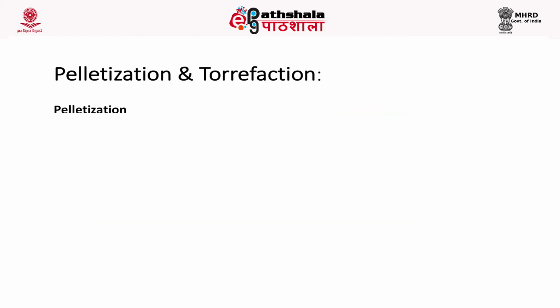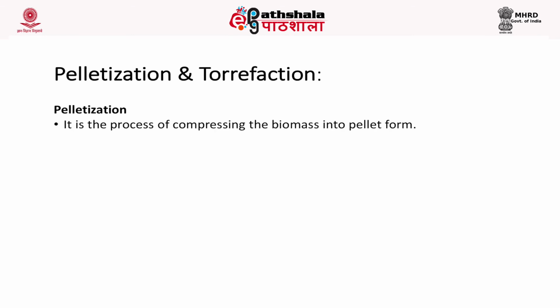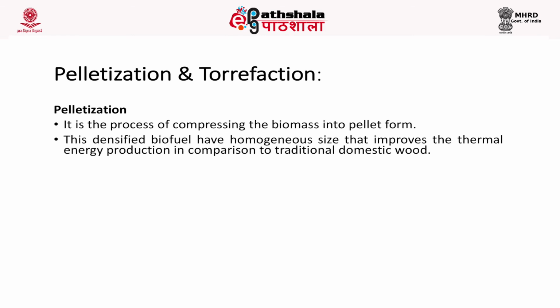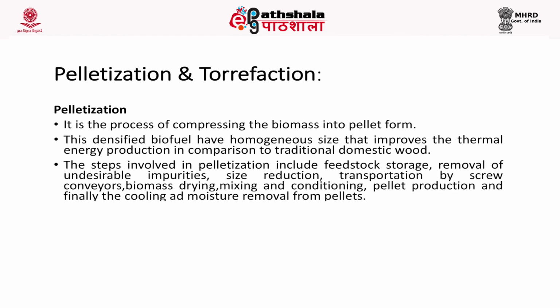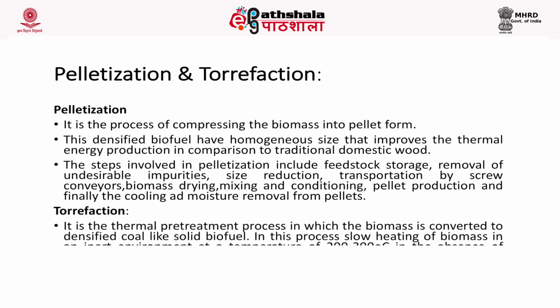Pelletization is the process of compressing the biomass into pellet form. This densified biofuel has a homogeneous size that improves the thermal energy production in comparison to traditional domestic wood. So it improves its efficiency. The steps involved in pelletization include feedstock storage, removal of undesirable impurities, size reduction, transportation by different conveyors, biomass drying, mixing and conditioning, pellet production, and finally the cooling and moisture removal from the pellets.